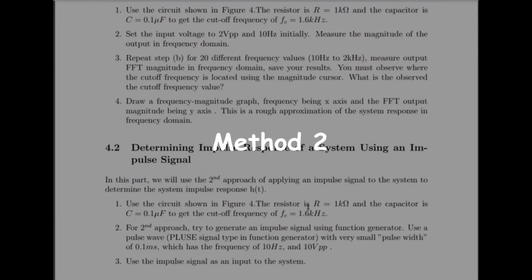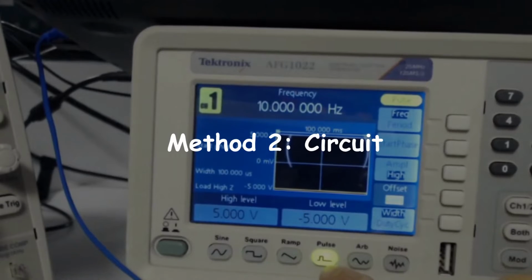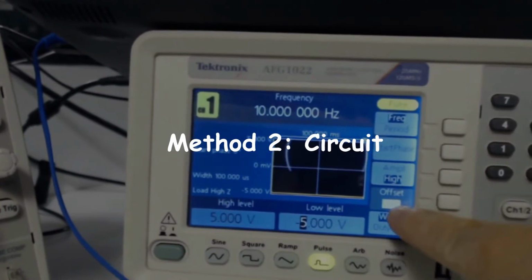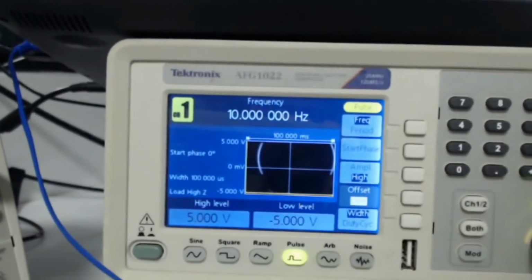So the second part, we are going to use the unit impulse signal as an input, which is a delta function. According to the convolution formula, if we convolve an impulse with a system, what is the output? The output is the system's impulse response itself. Here you can see it's called pulse, and we can change the width of the pulse. Impulse means the width is very small.